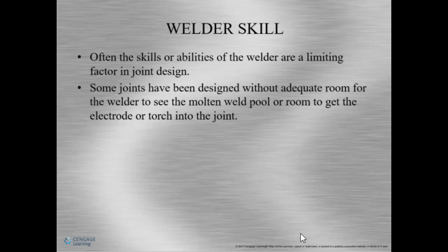Okay, here we go. So sometimes the skill of the welder may also come into play when deciding what type of joint, okay? Other problems with joint design is that the joint was designed by an engineer and it works on paper, but there's no adequate room to be able to access the joint or even see what's going on. So sometimes it has to go back to the drawing board and the engineer goes, well, I can draw it. Theoretically, it should work. Well, that's the problem. Theoretically, it works, but you can't get in there. So sometimes joints have to be accessible.